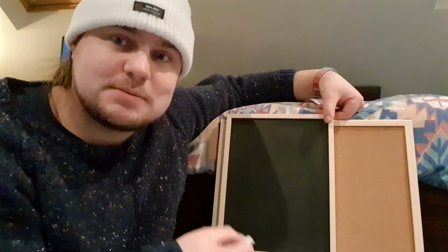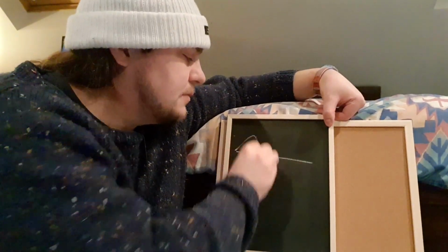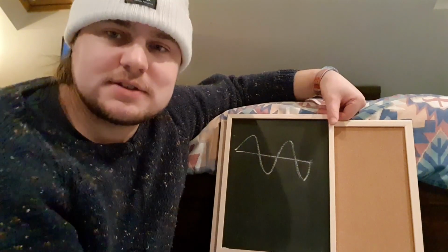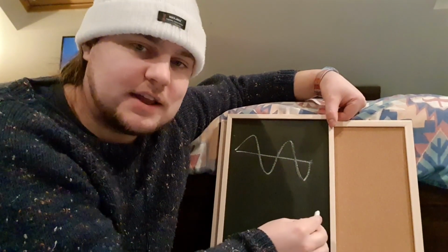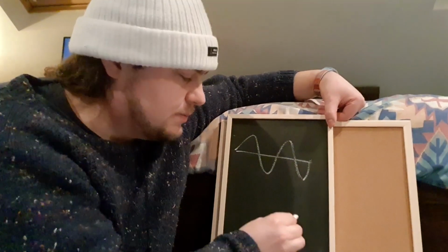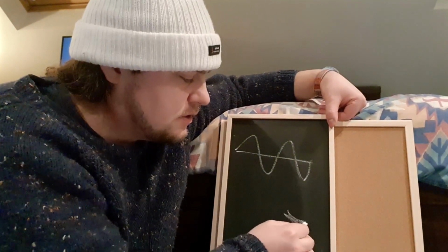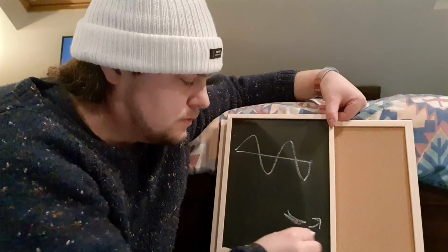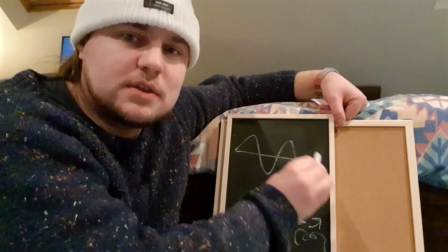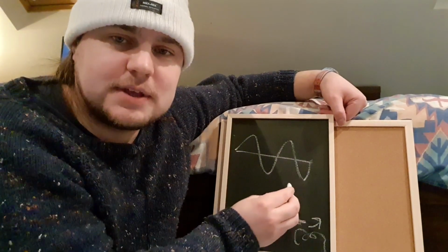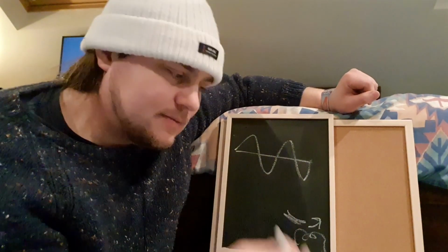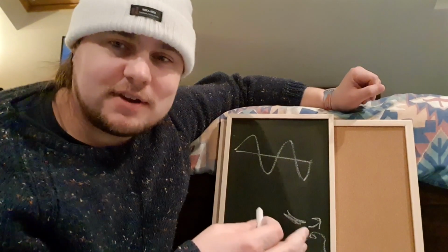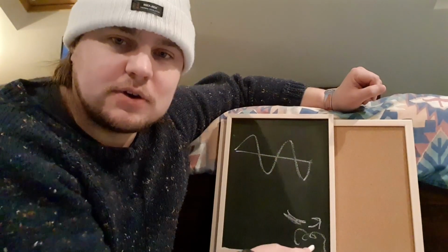We talked about how the power stations are all creating this alternating current, and they're all spinning at that speed. Imagine everyone's doing this, and that is physically related to a spinning magnet going past a coil. That means that all the power stations have to be in sync with each other, and they're actually magnetically linked together, because inside the generator you've got a magnet going past a coil.